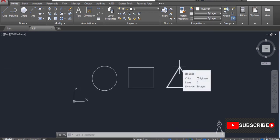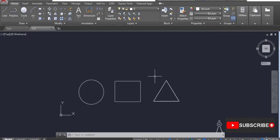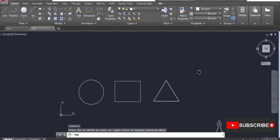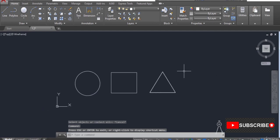In order to pan this drawing, or move this drawing in the drawing area, simply press and hold the mouse wheel and the cursor will change into this hand, and now you can move it in the drawing area like this. You can also access these navigation tools directly from the navigation bar. So here we have this pan tool. Simply select it, and now you'll be able to pan the drawing.